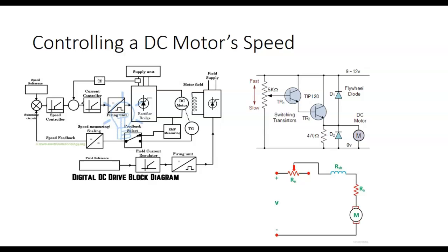but we had some cranes out there. They were 5-speed cranes, and that's all they did. They just had relays out there, and they would switch resistors in and out of the armature. And they were inside cages, and they got hot. They had fins on them. It's very inefficient to control the DC motor that way, but the circuits are really easy.